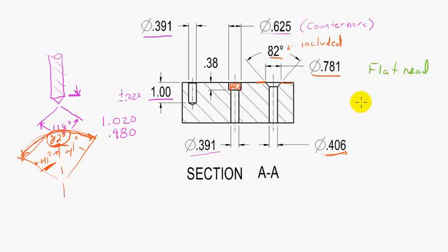Those are screws where the head looks like this, right? And they could have a slot in them, or they could have a hex socket, but the head has this 82-degree angle on it, and then the threaded shank of the screw is like this, right? That head, that 82-degree head, fits right in here.